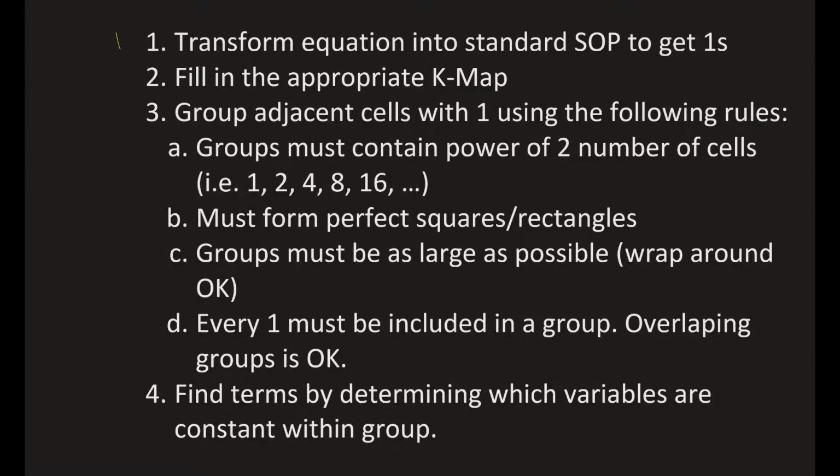You need to transform whatever equation, whatever circuit you have into a standard SOP to get all of the ones. Okay, step 2, we've got to fill in the appropriate K-map. So that's what we've been practicing for the last half hour or so. All right, here's the new stuff. We need to group all of the ones.